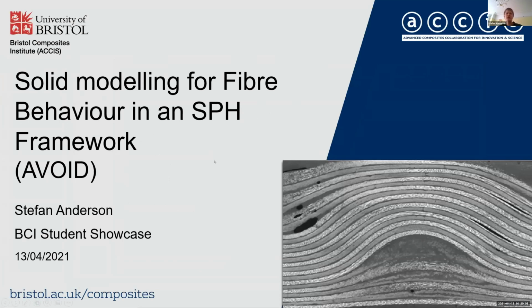What we're aiming to do at Avoid, which is funded by the EPSRC and Rolls-Royce, is to be able to simulate exactly what happens to voids during the curing process of the composite. Specifically, we currently have an excellent SPH model that can handle resin behavior and gas behavior. I've been trying to get a model that can handle the behavior of layers of solid fibers, for example, this ply layer or what have you.